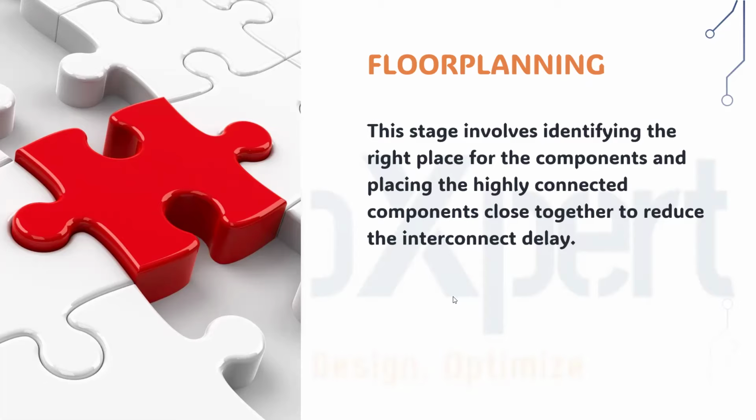Let's take an example. There is a chip like this. In this there is a section of RAM, and it has to be placed in the right way. All the RAMs have to be placed in the right way so that the other standard cell areas will be free for the connections. The logic is going from the input to the output like this, and it has to be placed in a proper way. That's how the floor plan will be done, the planning for each of the modules.